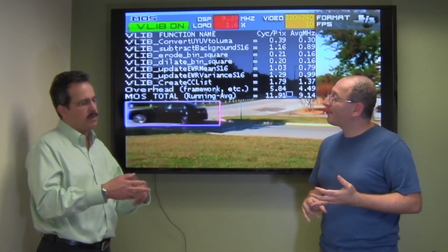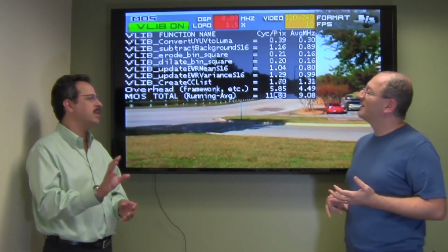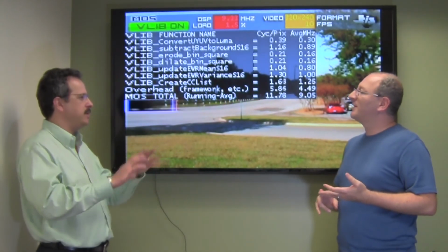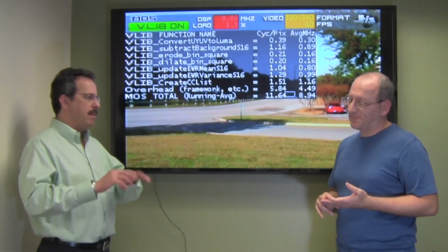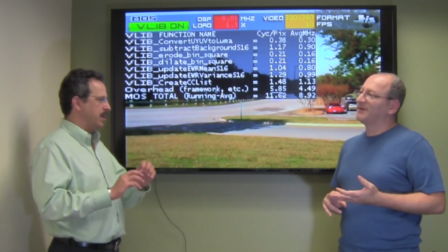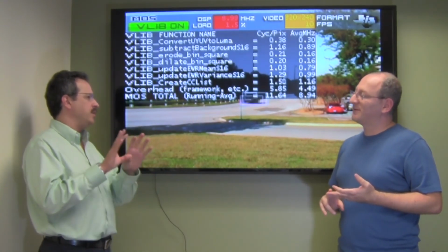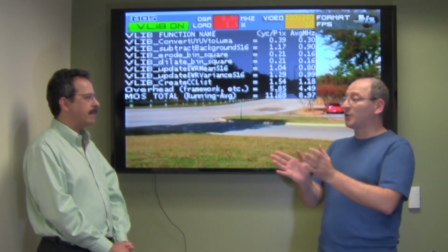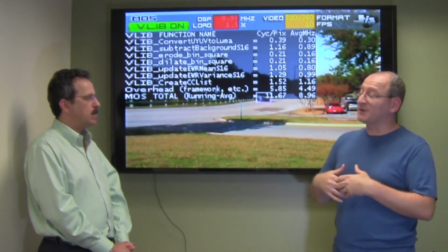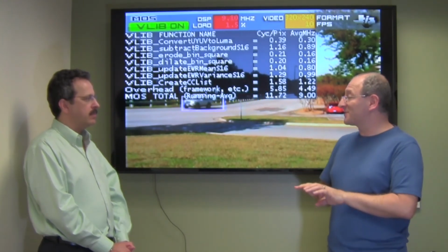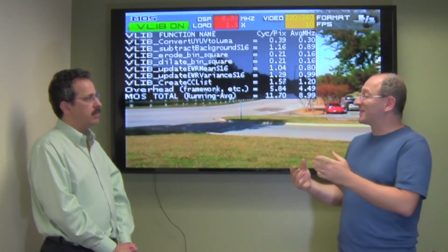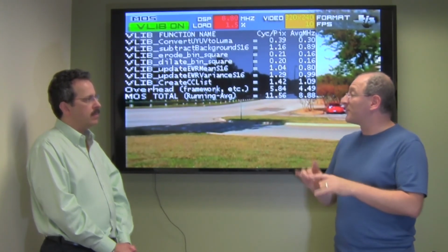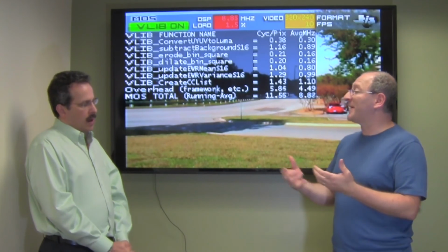So the intrinsics give you the ability to tell the compiler, hey, use this particular instruction that I know the processor has. It allows me to do 4 additions in parallel. But I don't have to get involved in writing the assembly code. I just basically tell the compiler, use this instruction. Exactly. So this data type looks like a 32-bit integer, but I know that internally I have 4 8-bit pixels packed in there. So I might want to do an MPY4, for example, which does 4 parallel multiplication operations on those 8-bit packs separately.